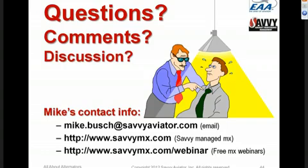Okay, and Sean would like to know, do you have a recommendation about replacing belts only when you replace the alternator, or just as needed? Well, my general philosophy is to replace stuff only as needed. So I'm real big on inspection, and I'm not very big on prophylactic replacement. I believe we inspect things, and when they start to show signs of wearing out, then we replace them.